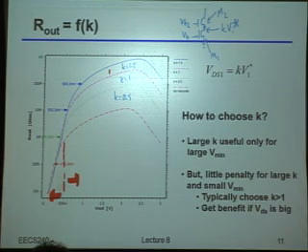So to put this another way, you really do want to choose that higher bias voltage, simply because there's really not much penalty for doing it at any of the lower voltages. And if you happen to get a larger voltage across the structure, you will indeed get a higher output impedance from it.